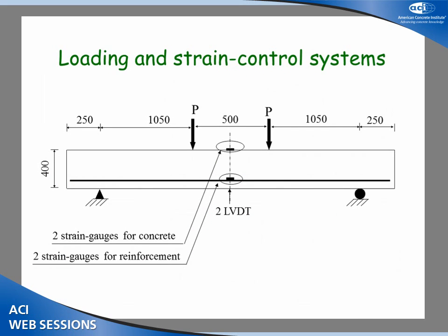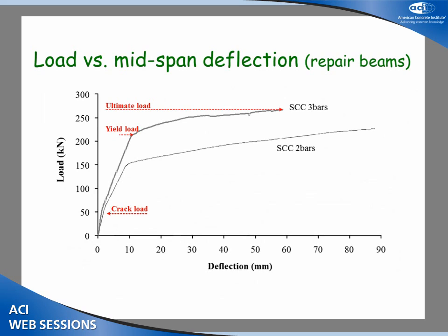And then after the proper curing, we did the structural performance, three-way bending. And these are typical results. So you would get a load deflection with 3 types of loads. The first load where the cracking occurred, the load where the steel started to yield, and the ultimate load where the maximum capacity was reached.